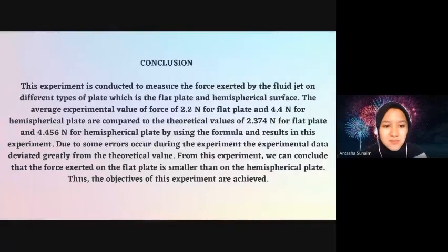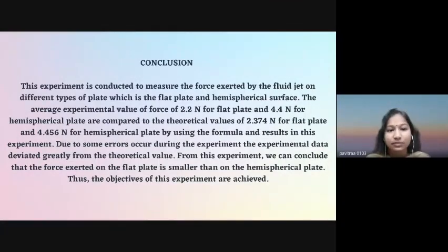In conclusion, this experiment is conducted to measure the force exerted by the fluid jet on different types of plate, which is the flat plate and hemispherical surface. The average experimental force of 2.2 Newton for flat plate and 4.4 Newton for hemispherical plate are compared to the theoretical value of 2.374 Newton for flat plate and 4.456 Newton for hemispherical plate by using the formula and results in the experiment.